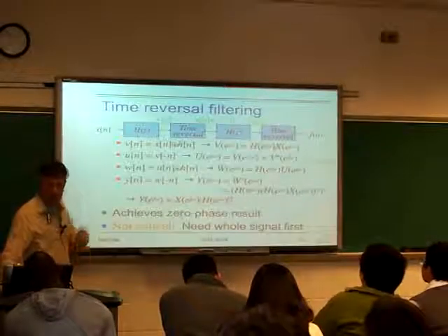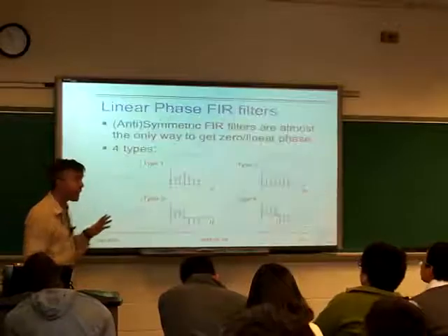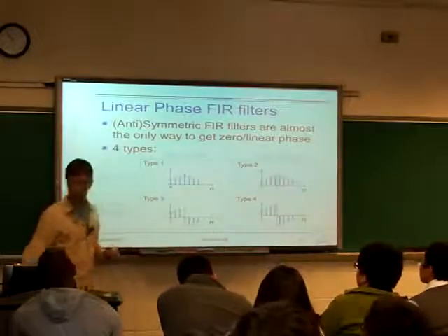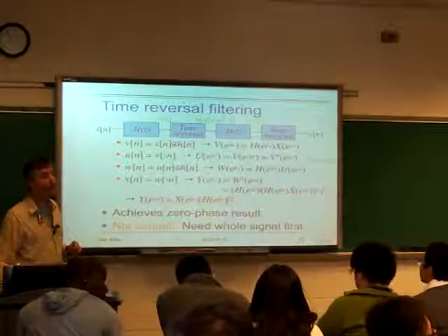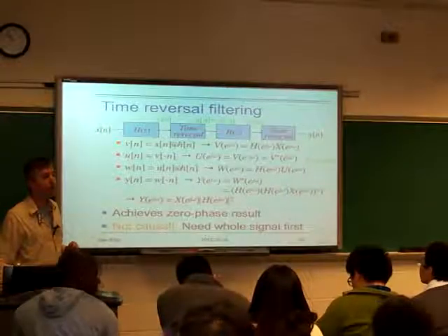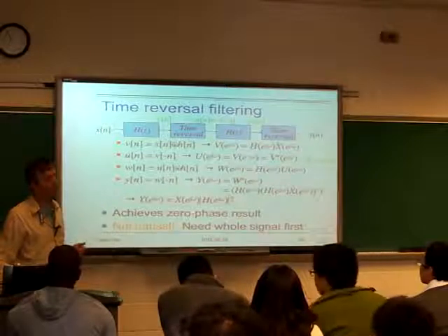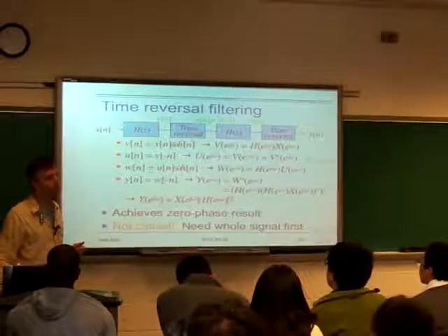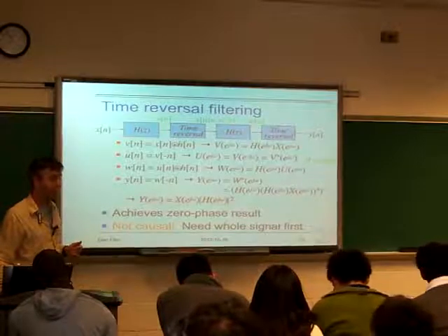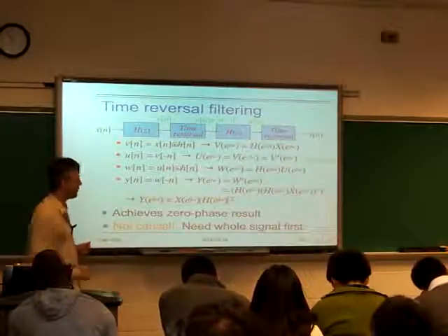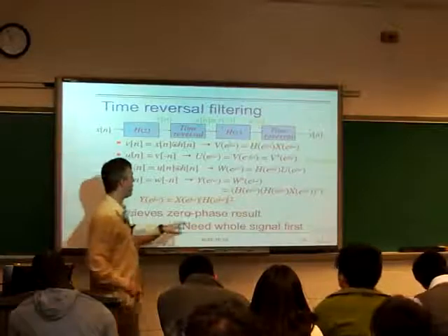That's one way of doing it. There's another way we can do it. Sorry, by doing this time reverse filtering, we're actually altering the transfer function itself. Like instead of getting H(z), you're getting H(z) squared. I mean, the magnitude response is actually squared. That's right. So how do we get over just getting the magnitude response and letting go of the phase?